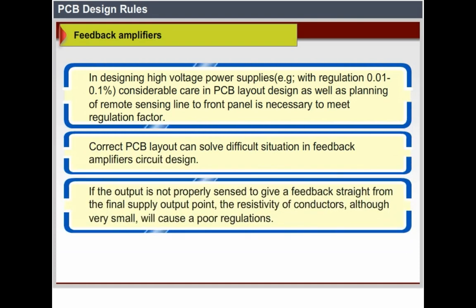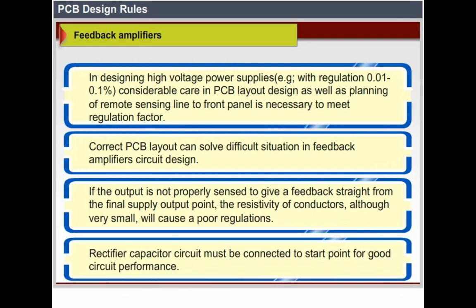If the output is not properly sensed to give feedback straight from the final supply output point, the resistivity of conductors, although very small, will cause poor regulation. The rectifier capacitor circuit must be connected to the star point for good circuit performance.